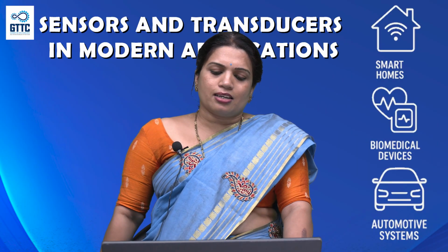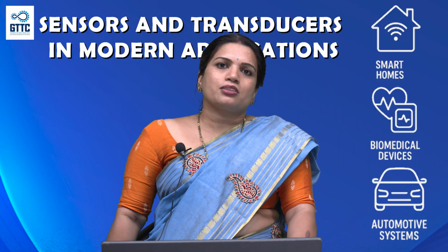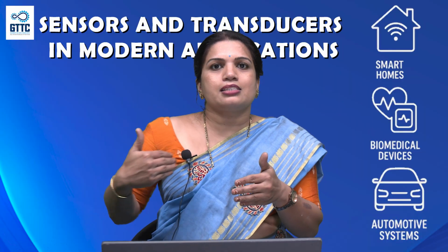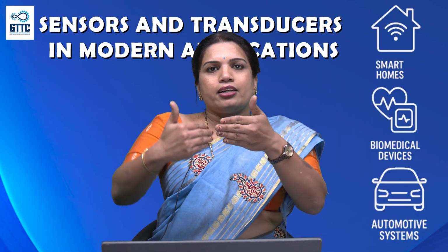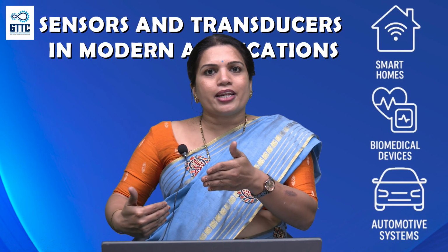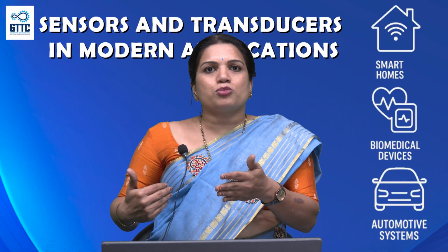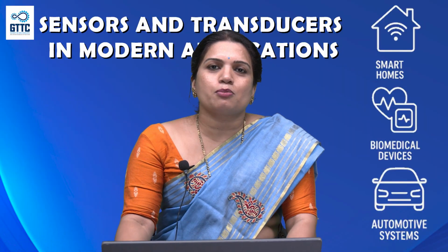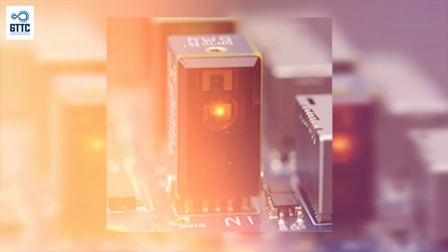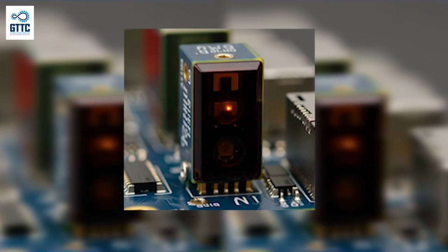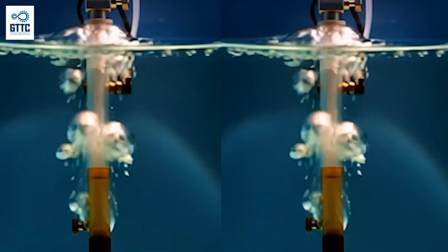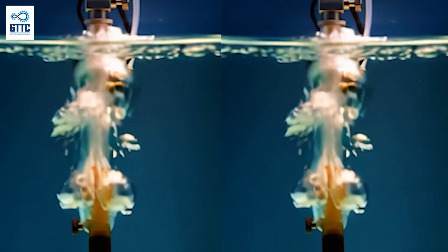What are these IR sensors? An IR sensor is based on the working principle of infrared rays. The IR sensor sends IR rays, and whenever they hit an object, they reflect back at a speed, and from that speed it calculates the distance of the object from the source. This is the principle behind the IR sensor. We have two types of IR sensor. One is the active IR sensor, which detects obstacles. The second is the passive IR sensor, most commonly used as the PIR sensor, which detects only the human body.